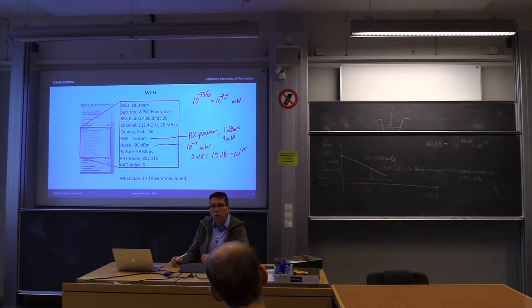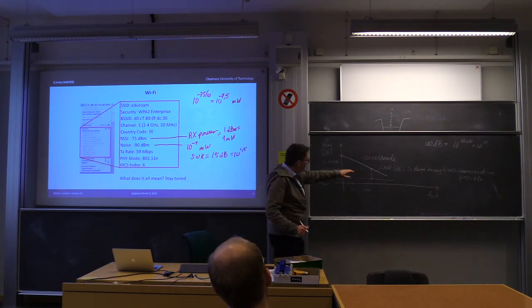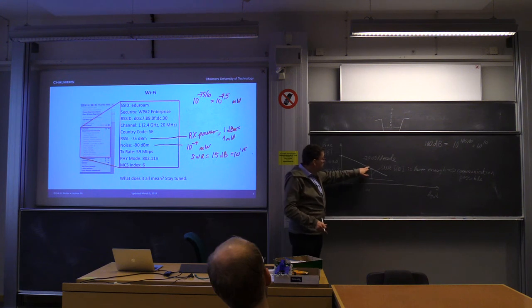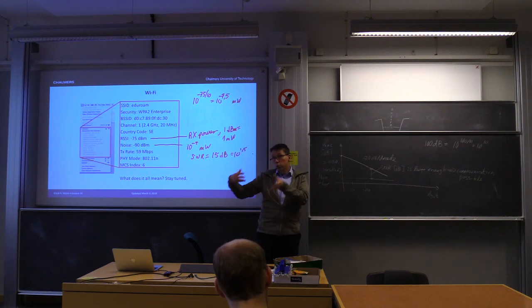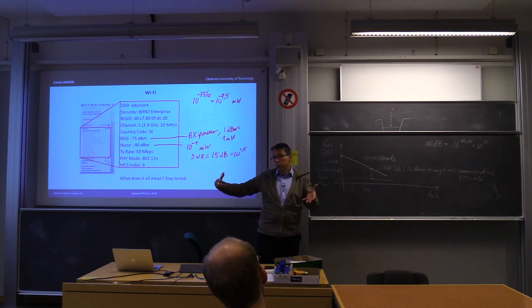It's not quite 100, but more than 10. That's the difference between the current received power and the noise floor in this plot. So when you move closer to the access point, you get better SNR; further away, lower SNR. And this has an impact later on, as we will see, on which data rate you can get out of the system.